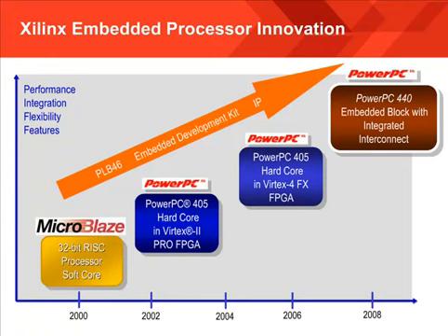The PowerPC 440 is available from the Xilinx Virtex 5 FX family and is dedicated in the silicon. This means that it can obtain higher performance and have a top speed of over 450 megahertz. Now, don't forget that the PowerPC 440 we use is the same as the off-the-shelf version. There has been no optimizing or simplifying of its architecture. It is literally the same ASIC, just fused to the FPGA's interconnect.